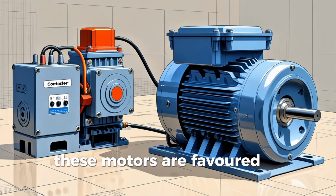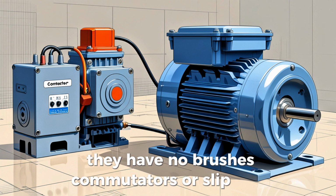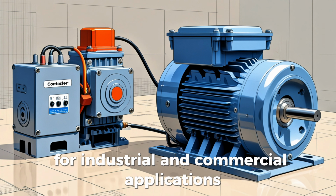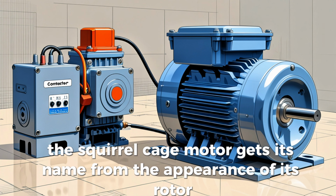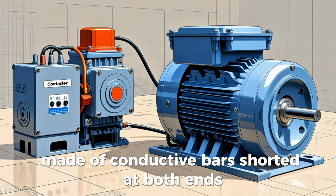These motors are favored for their simplicity, reliability, and rugged construction. They have no brushes, commutators, or slip rings, which makes them low maintenance and highly durable for industrial and commercial applications. The squirrel cage motor gets its name from the appearance of its rotor, which looks like a spinning squirrel cage made of conductive bars shorted at both ends.